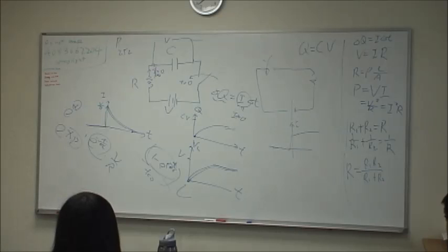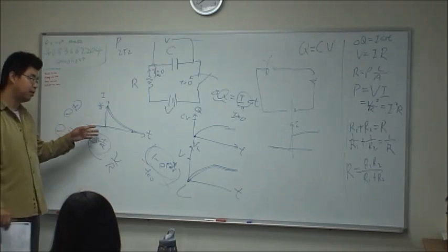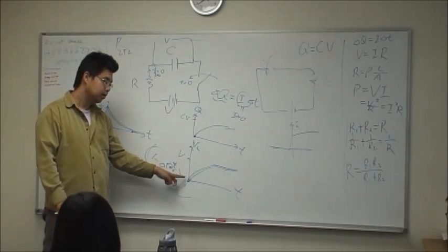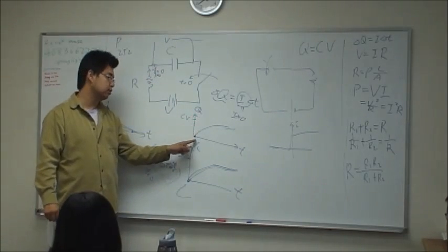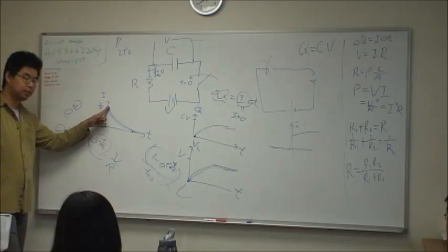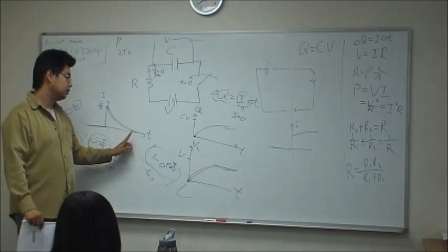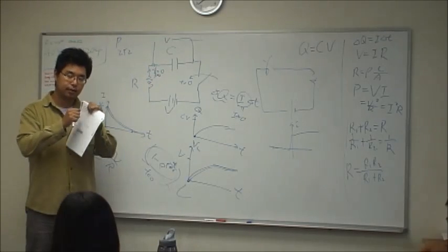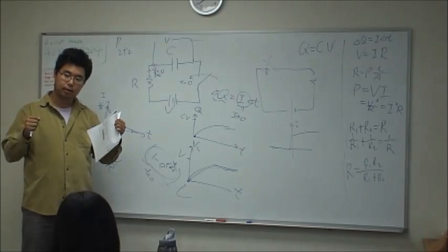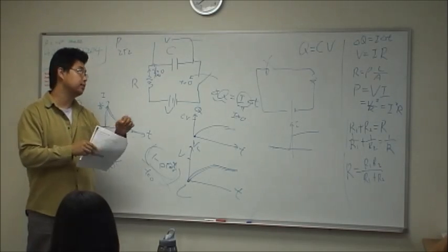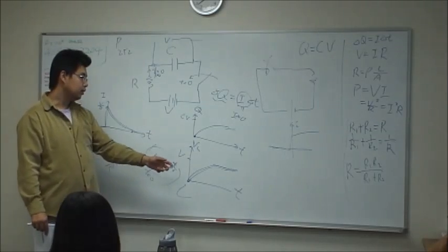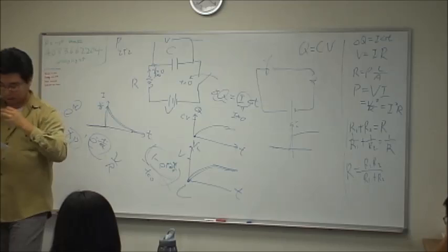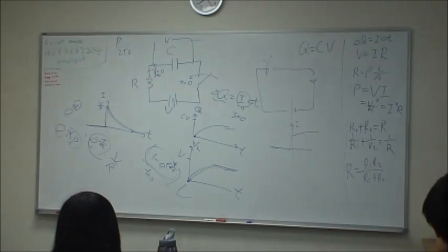It's the next level. But what I want to say is that it's important to state the initial state. For the capacitor, the voltage never jumps, and the stored charge never jumps. However, the current will jump. And what's the end state? At the end state, there is no current, which means the capacitor at the end can be considered as an open circuit. So the voltage will be just equal to the battery, and the charge is fully charged. Any questions so far?